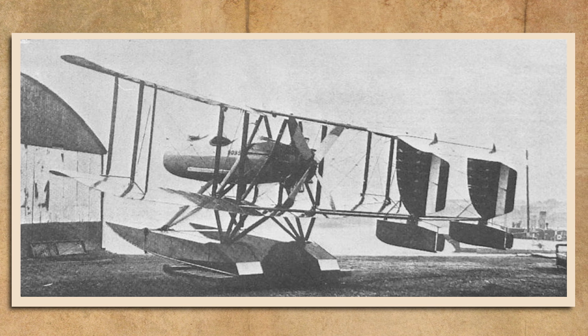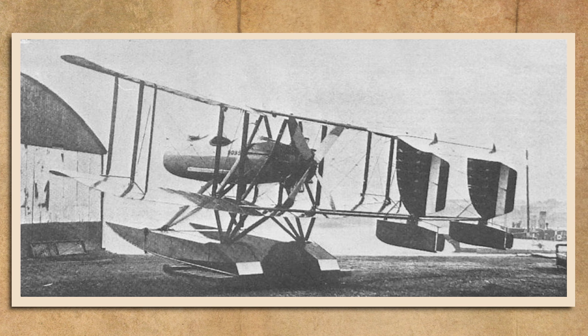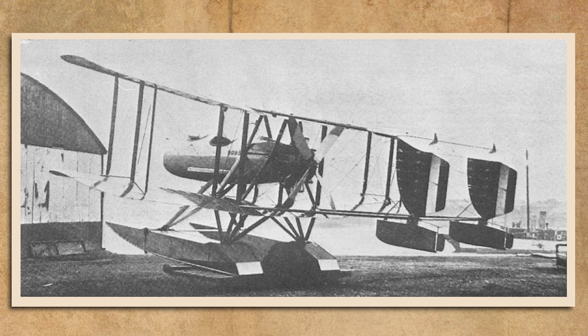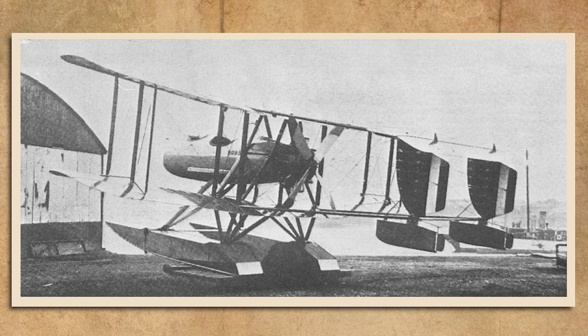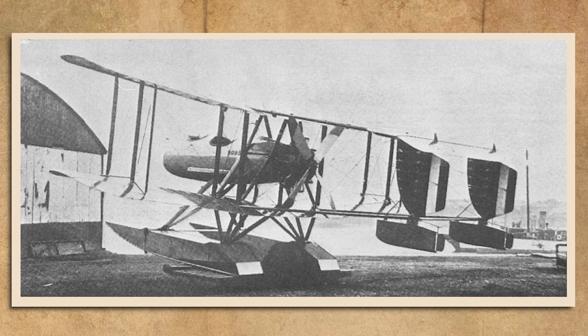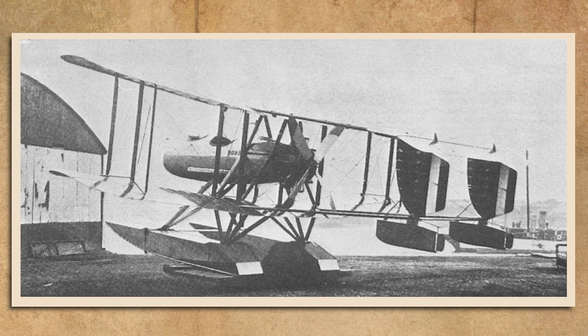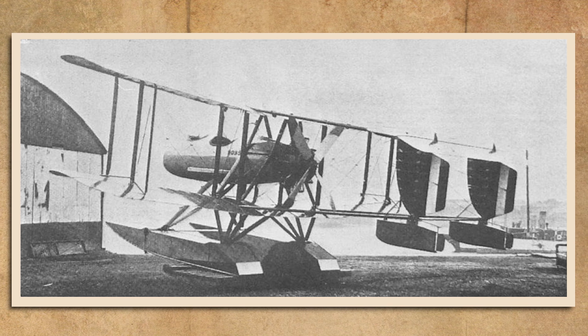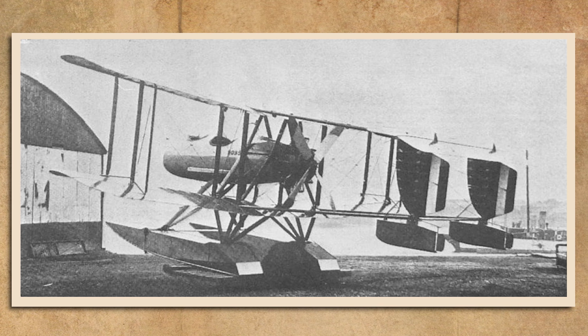To avoid the prop wash, which often interfered with tail control, the tailplane was raised up as far as possible. It was completed with pontoon floats, though there were originally plans to use those developed by Linton Hope, but the earlier models had proved to be unstable, and the Admiralty preferred their men and equipment to not sink.